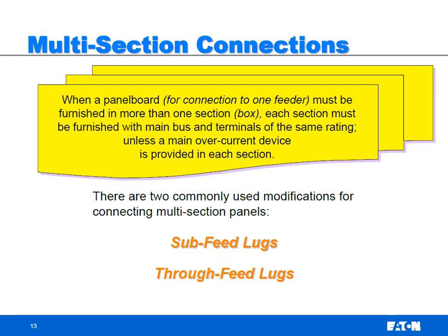Generally, most people are still following the 42 circuit rule because I think they've realized the 42 circuit rule had a lot of common sense in it. The space required, height-wise, how many cables can I literally fit in a gutter while I'm running out all my loads? How many conduits can I fit into the top?